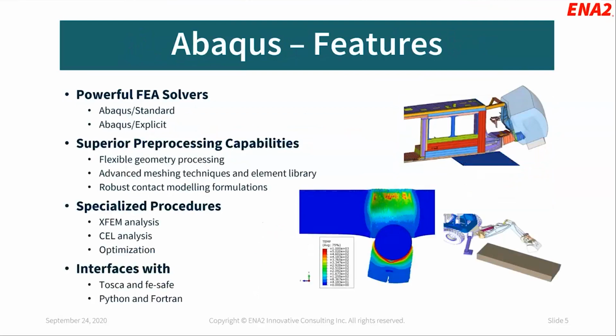First and foremost, Abaqus' main feature is its powerful standard and explicit solvers, whose ability to produce accurate results for highly nonlinear phenomena is well documented across industry and academia. Abaqus has both solvers built in under one software package, and this is helpful because if you have a multi-step analysis, you don't have to jump between solvers every time a step is finished.